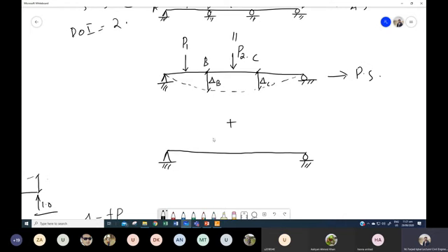So then we will have at point B a redundant reaction, let's call it By. Now again, like I told you, we can apply it in this direction or in the downward direction, whatever. It doesn't matter. The final sign will dictate the actual direction. So it depends on you.